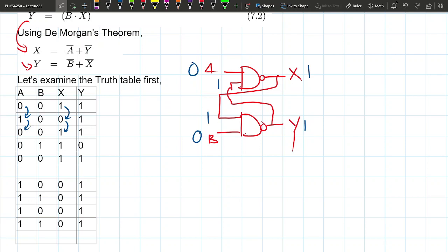All right, well, okay, that's kind of boring. All right, let's see what happens if I did this to B, right? So if I flip B from 0 to 1, right, that means this is a NAND between 1, 1 now, right, and the output of that is 0, right, and that brings it back here and makes this input 0. So changing B from 0 to 1 changes Y, right? Okay? It seems like me switching this up and down changes what this is on the opposite, okay? Similarly, if you flip this back to 0, it changes Y back to 1, okay?